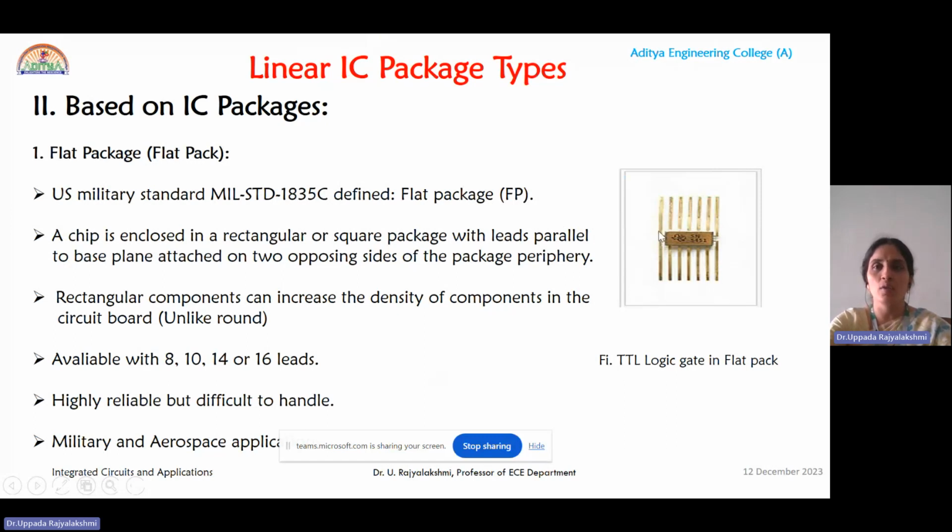Because of its structure, you can see that it cannot be easily fit into hardware. If we fit one side of the pins towards the board or breadboard, the other will be on the top side. So it cannot be easily fit into hardware because it's difficult. It's not suitable for commercial applications. It is only suitable for military and aerospace applications. This is available with 8, 10, 14 or 16 leads. It's highly reliable, but the only thing is it's difficult to fit into hardware, so it is less preferred for commercial applications.